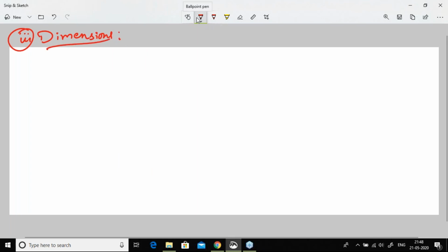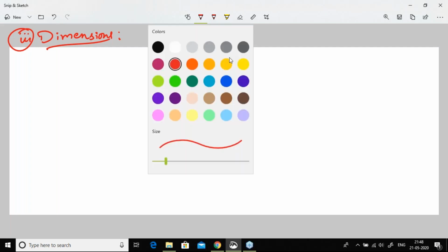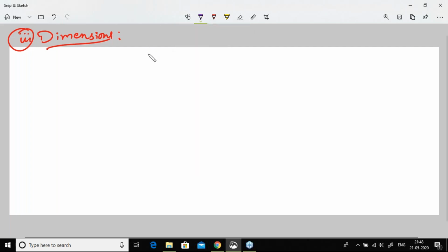These dimensions we will get from table 23.1, like addendum, dedendum, tooth thickness, total depth, clearance, outside diameters of pinion and gear. So everything we will get from table 23.1 for the given system of gear we have to calculate.